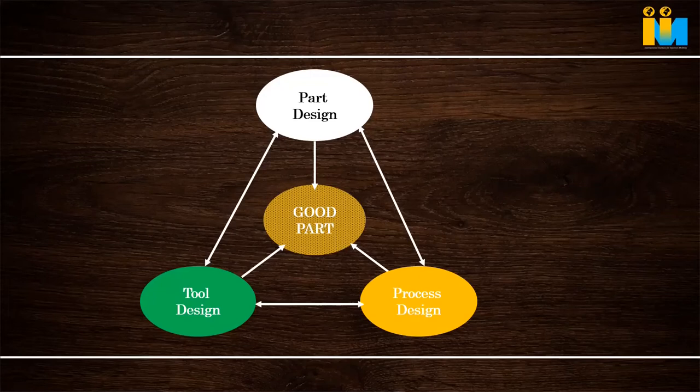If the tool is qualified properly and the part design is right, then processing people don't have to put in extra pressure, and the processing window is not very narrow. Whenever there is a narrow processing window, where my process molding has to be set so critically to get a quality part, it is going to deviate and rejection or failure is going to come.